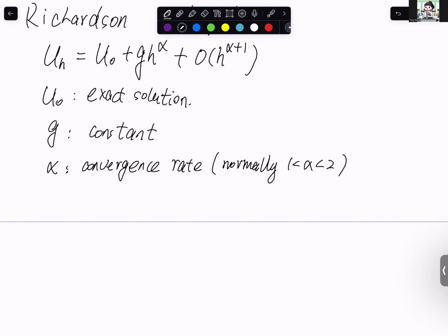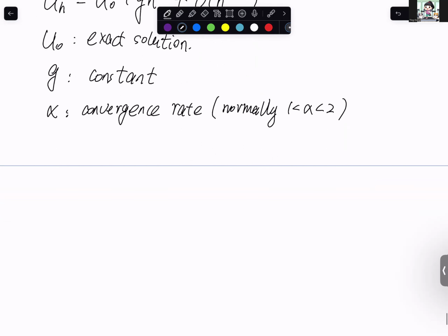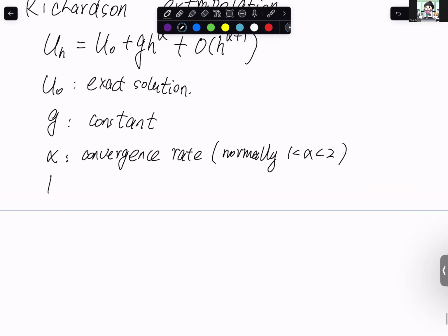did everything correctly in the convergence study. And also, different mesh, different element type you use may change a little bit. So in the project, if it's a little bit higher than 2, you should be fine. It does not need to be exactly between 1 to 2. So now the h here is a very important parameter, the element size.